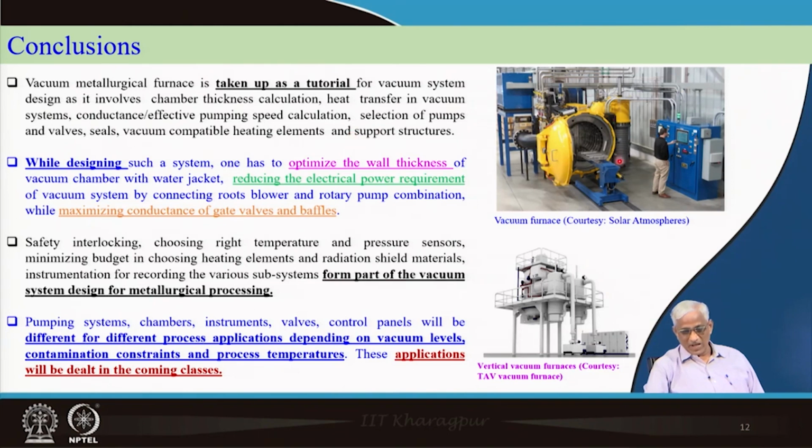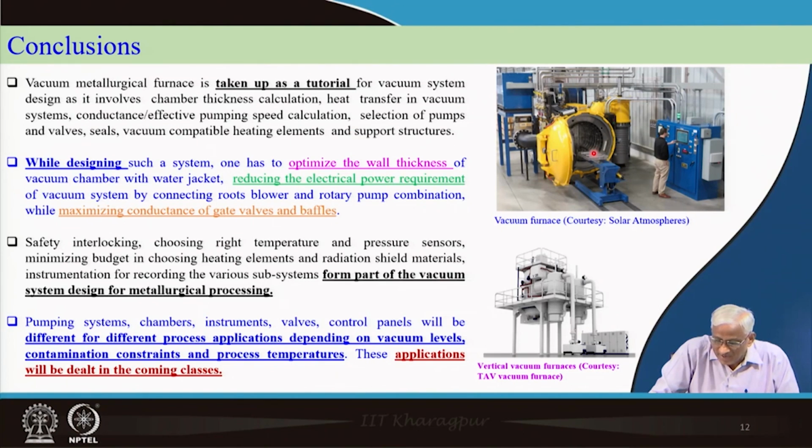The furnaces will look like this. You can see here there is a big rail type of structure. Whatever you have to send, you can send it inside. There are heating elements and shields, front door and pneumatic couplings and variety of electrical pipelines and water pipelines and pumping systems and big elbows and diffusion pump here, then backing rotary pump and roots blower will be on the other side, heating elements, electrical transformers for power supplies, and the entire thing is microprocessor controlled, and he will see the